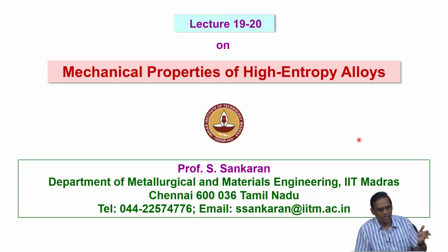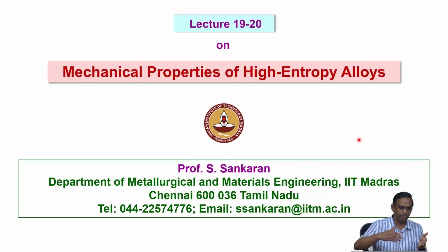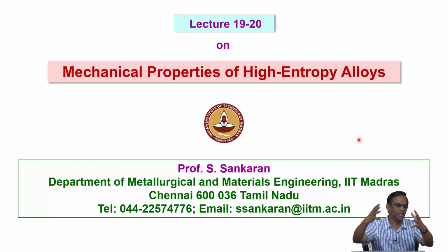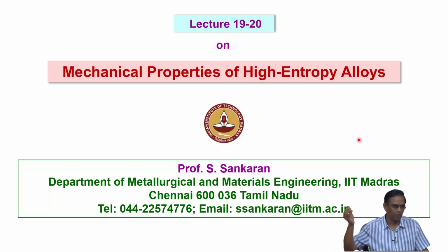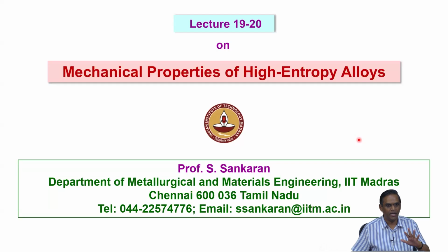So when you talk about a dislocation core, you have two kinds of stress fields. If you consider a classical edge dislocation, the upper side is experiencing compression and the lower side is in tension. So all the substitutional elements can go and occupy the tension region, so that it will reduce that stress, it tries to relax that stress. Similarly, any small atoms can go and occupy the compressive stress field, so that will try to relax it. So this kind of idea we should know.